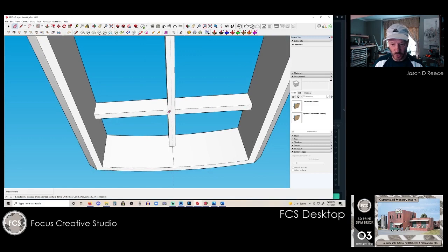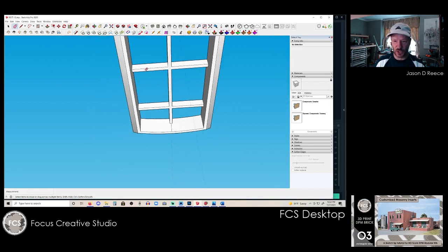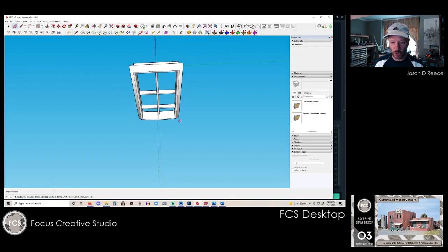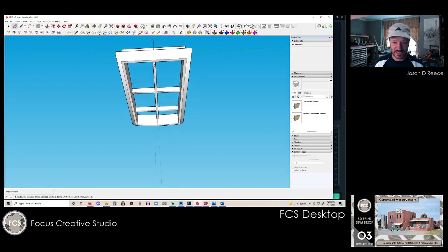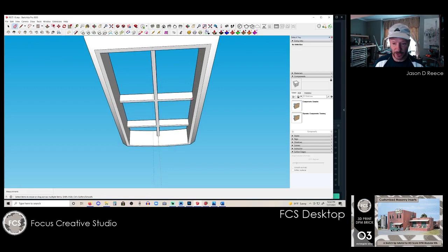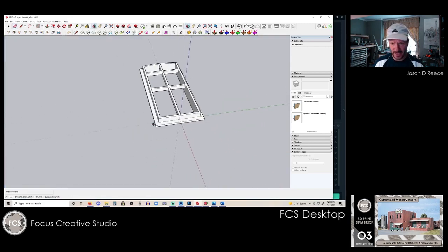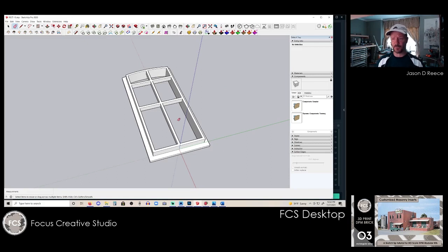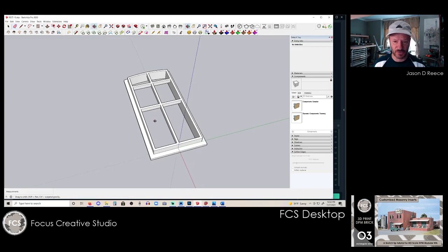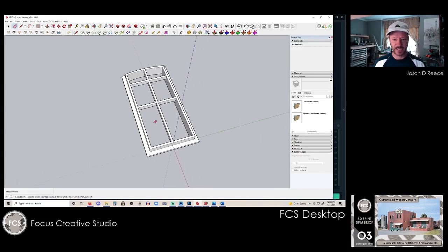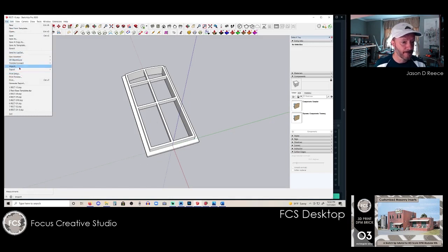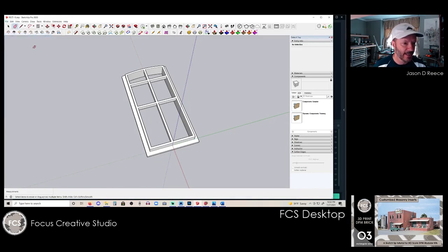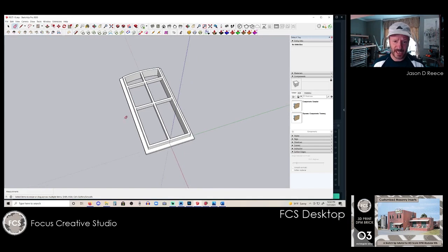I don't do anything special with a landing pad for supports on these particular models. Again, I have that whole perimeter where I'm going to load up with supports, and then I place some light supports in here and load these up with a tree-like structure. I'll probably go through that in a completely separate video on how I design and detail windows specifically for supports. But this at least gives you a real quick idea of how I set up my windows and some of the tolerances: 0.5 millimeters wide, 1.2 millimeters deep. That gets us some pretty clean detail when we print these out.